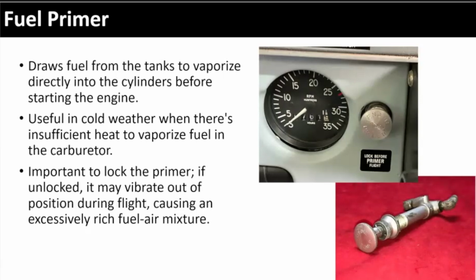that primer is locked, because if it's not locked and it becomes loose, it could allow excess fuel to be pumped into the system. Okay. Every plane that we have here on the line has a primer. No, I take that back. The Warriors have a primer, the 172s do not. So you need to make sure that after you prime the system at start, that thing's locked.